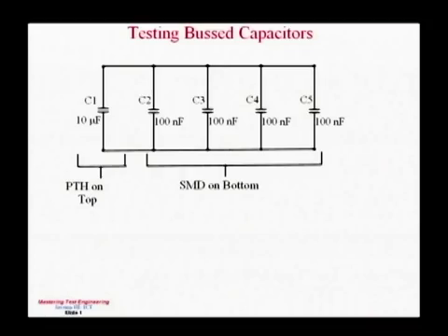So another example of the idea of testing a board when it's half built, when it's going through the manufacturing process, is when I don't have parts loaded on both sides, sometimes I can test all kinds of devices that I can't test when the board is fully loaded. And capacitors are an obvious example. If all my surface mount caps are on the bottom of the board and I build the bottom first, then when my pin-in-hole devices like the polarized capacitors are loaded, well, they're in parallel with all those little caps. I can test these little caps that way. So these are just more and more techniques to try to push those faults back and find them early in the process. And you'll find that as you do that, you're saving your company money.